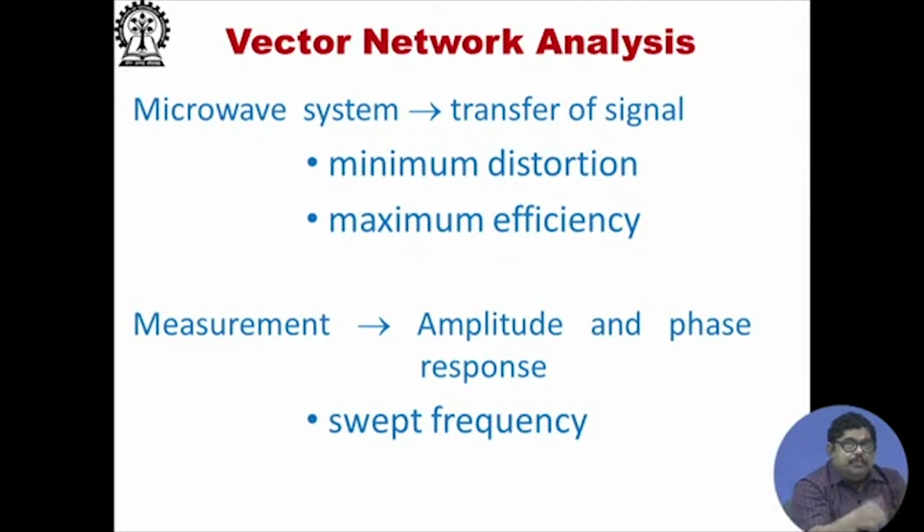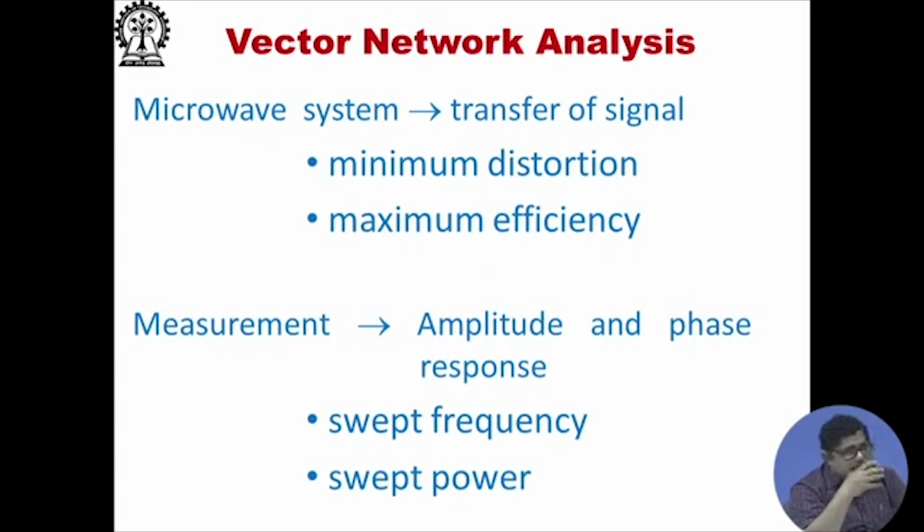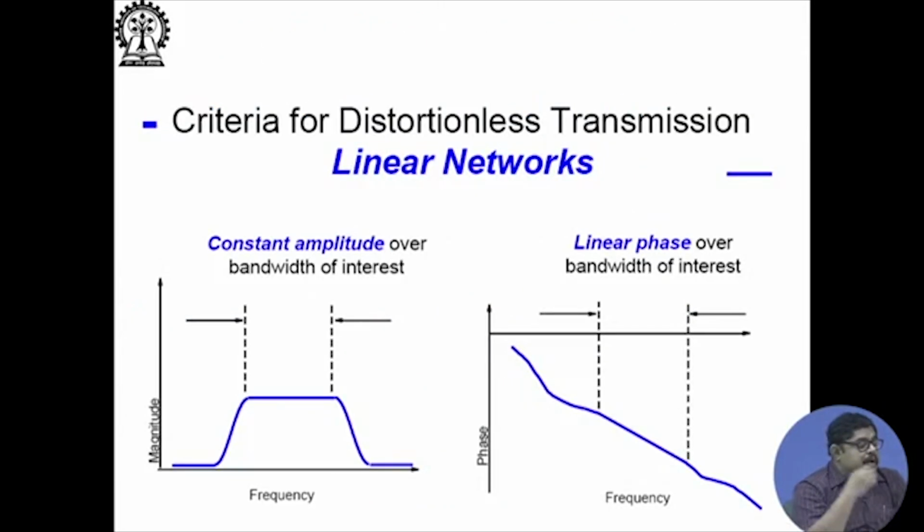Either we can sweep frequency, that means we can get amplitude and phase frequency response, or we can sweep in power, that means amplitude and phase power response, which is also called linearity characteristic, because if I go on increasing the power, after some time the device becomes non-linear. So, that testing is also important, because that will give me an idea whether I will be able to do the transmission without any distortion in the signal. That means, quality of the signal should be kept.